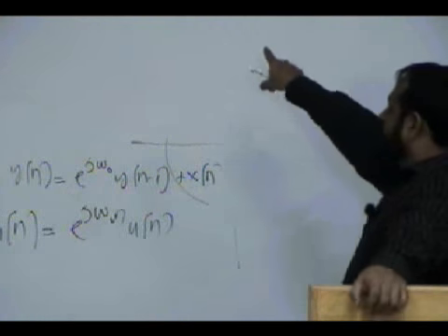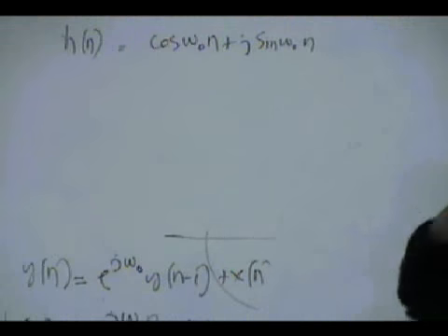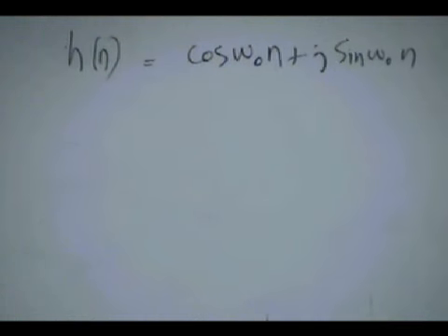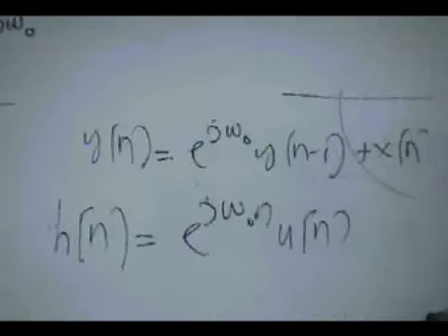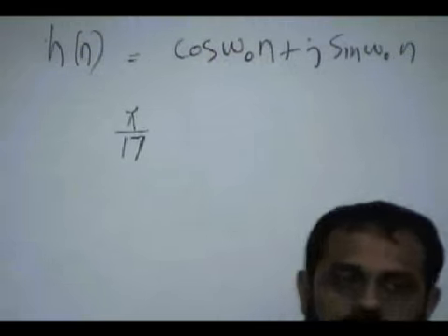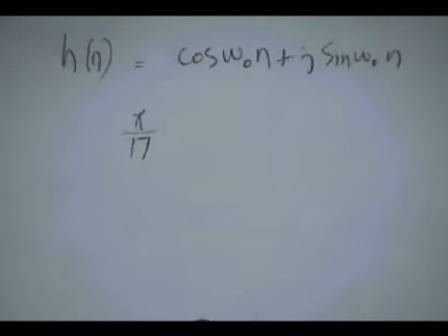So coming back to this, okay, if in MATLAB I want you to generate sine and cosine, you design this particular filter. I ask you to generate sine and cosine with frequency pi over 7, for example. Design a first order IIR filter which can generate a cosine and sine of pi by 7. What do you do?